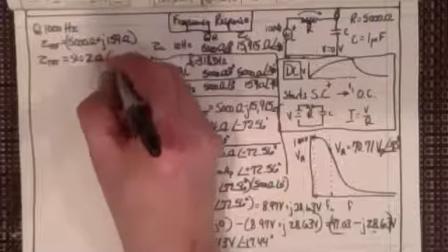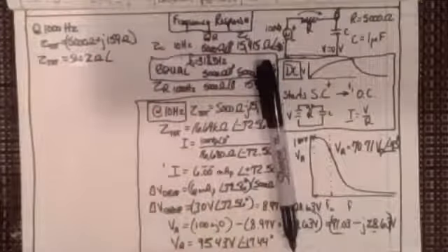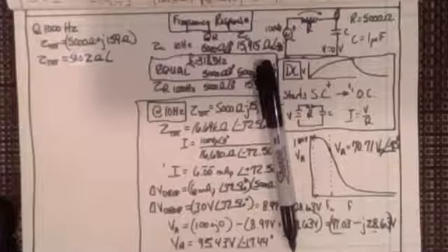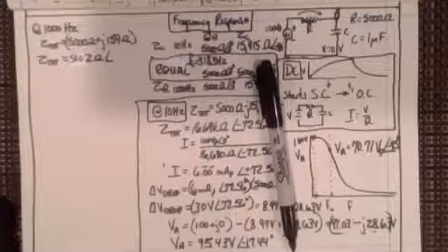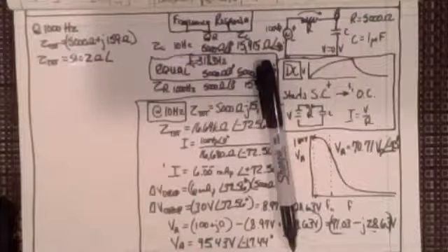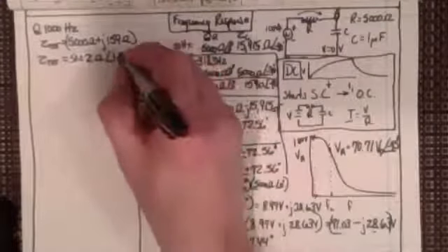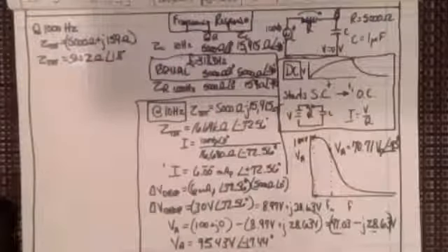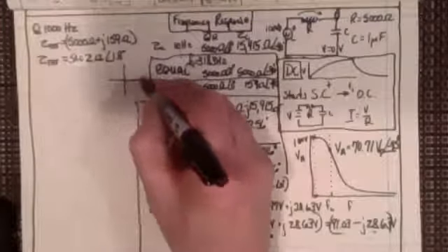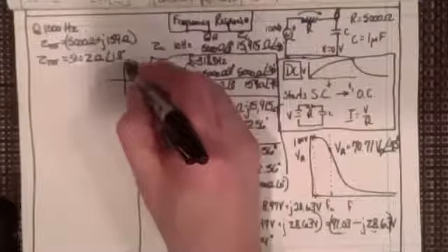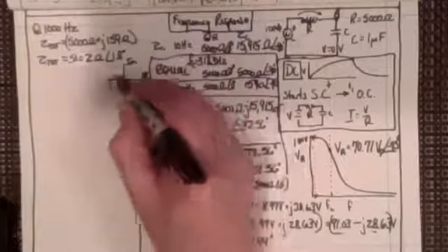5,002 ohms and an angle that's got to be very close to 0, doesn't it? Right? 159 divided by 5,000, and then take the inverse tangent of that. That gives me 1.8 degrees. So very close to writing straight on real numbers. I should write the complex plane here to remind you how it works. There's my real, there's my imaginary, there's my complex plane.